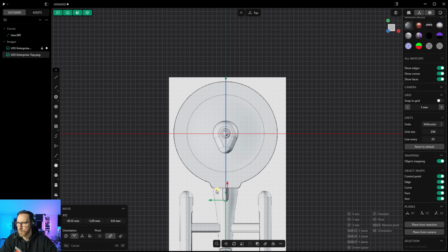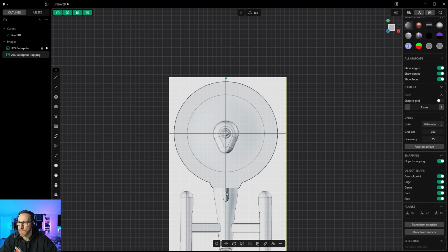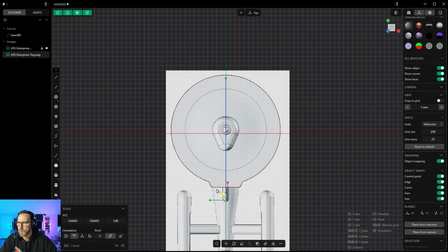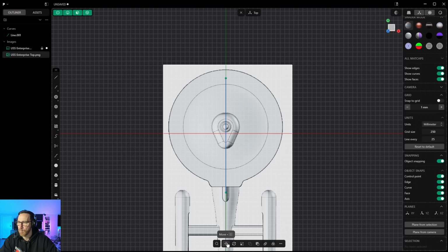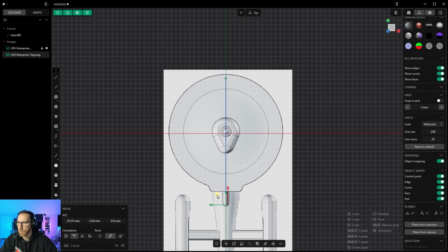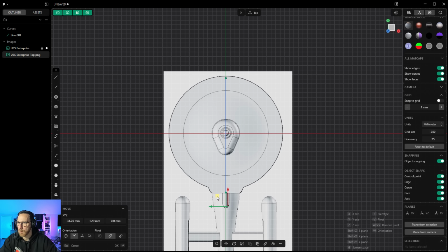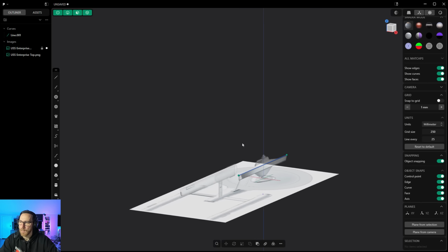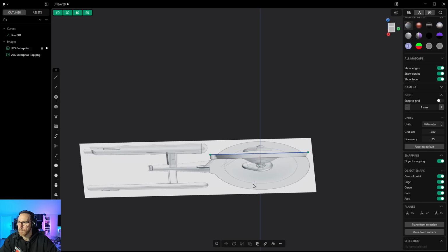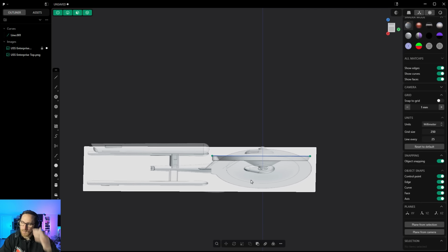And what we want to do is recenter this and see how close we are. All right, so you can see we still have a little bit of scaling to go. So once again, scale. You can do it this way. I suggest getting comfortable with using S on the keyboard, then move, which is G on the keyboard. And again, hitting G twice will let you basically lock it to your cursor. Right click, and that looks pretty close. And so as we rotate these around, now they look to be roughly the same scale.